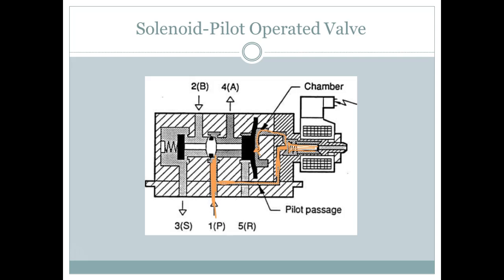You understand? We've got all this pressure out there. This is what we call a pilot. Can y'all see that? So this is the actual solenoid. This is representing the coils of wire up here for the solenoid. That's all that does. And this would be a pilot operated, spring return. And there's the spring over here.